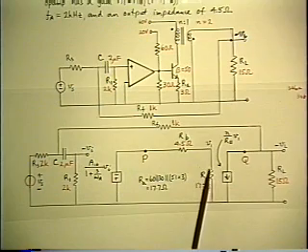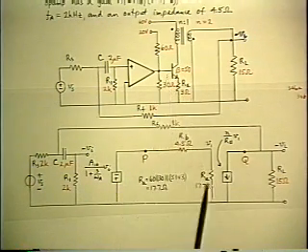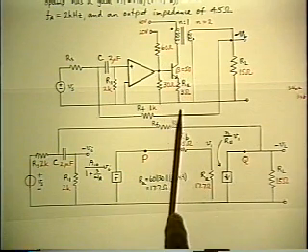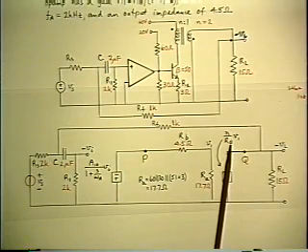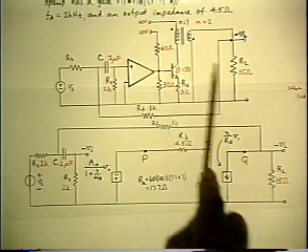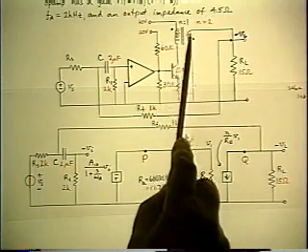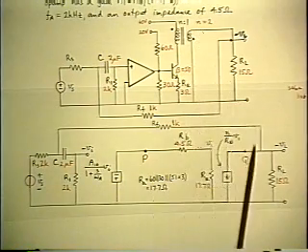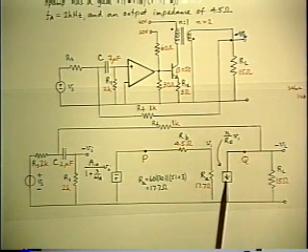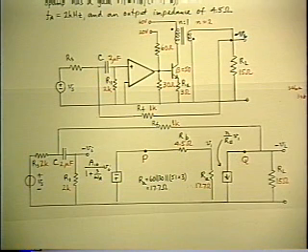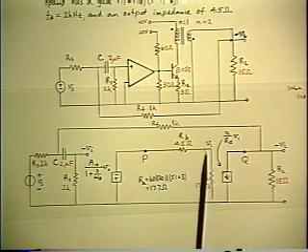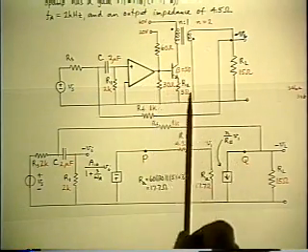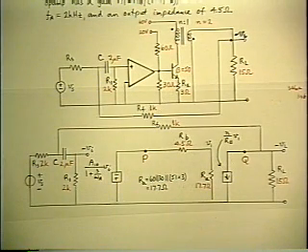So now we've got the representation of the input resistance to the power stage. So V1 is going to develop a voltage across RE of V1 over RE, which will be the emitter current. Multiply that by alpha, which is 1. Multiply the collector current by the transformer ratio, which is N. And so that factor determines the secondary output, and the transformer is included in the current generator coefficient. So the input resistance and the output current is all you need to represent the gain properties of the power output stage.